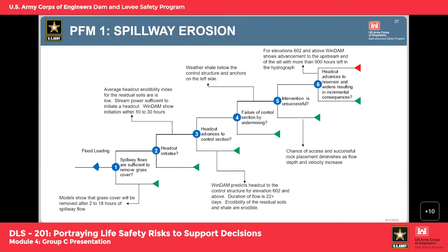It's typically limited to 3,000 CFS, but has a much greater capacity, so that could help offset inflows. And there's also a possibility to place materials via helicopter. However, intervention is less likely in general to be successful as flows increase.